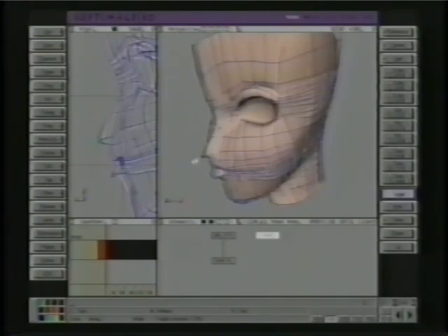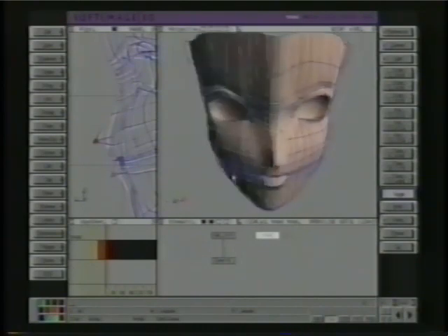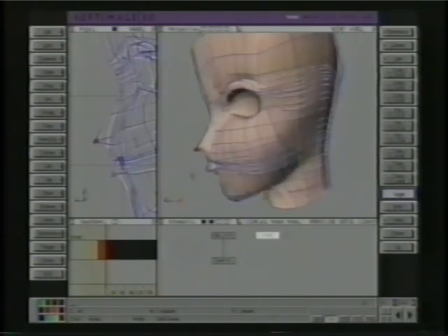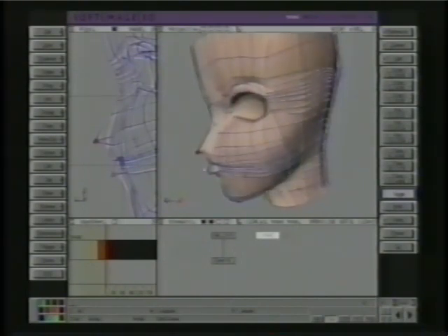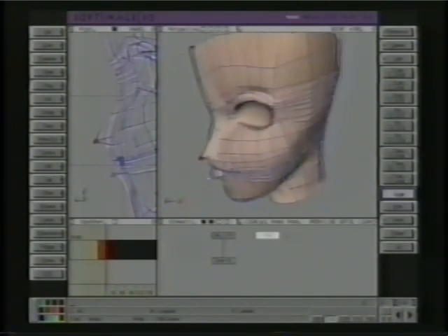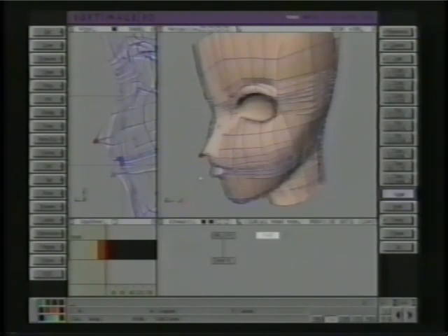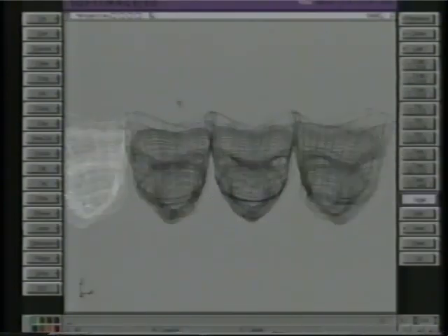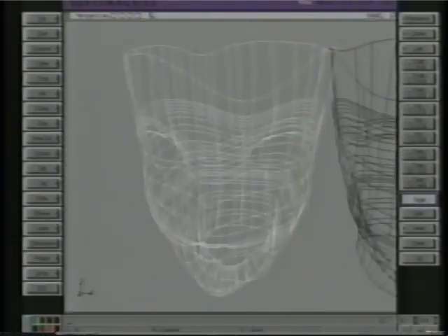This should be used selectively, however, because it actually pulls the knots of the surface surrounding it, and so it'll actually distort the texture map right around there. But you can use it on eyelids and lips and noses and things like that to get a tight fit when you need to. Now I'm going to talk about parameterization a little bit.